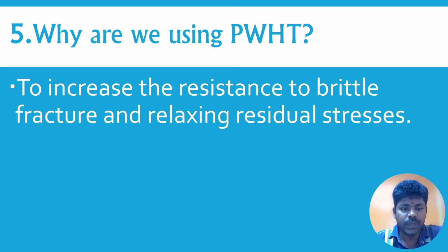Why are we using PWHT? To increase the resistance to brittle fracture and to relax residual stresses. That is the unequal and equal, that is called relaxing residual stresses. So, to increase the resistance to brittle fracture and relax structural residual stress.